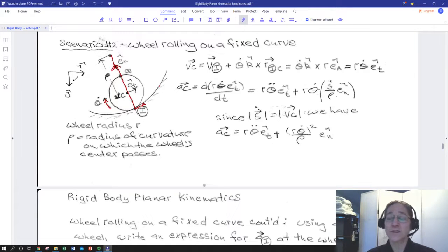Notice that's opposite of J. The two aren't even perpendicular yet, so we're not going to try to relate them now. So we do the cross product, and we cross K, which is positive going into the screen, with n that is positive going normal, and we find that our thumb is pointing in the positive tangential direction.